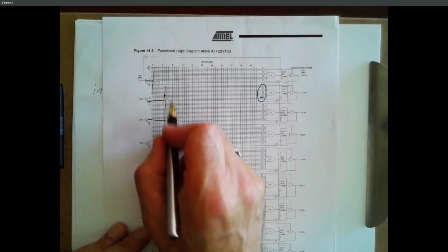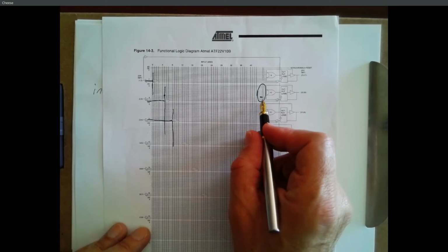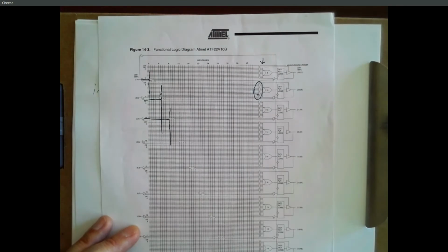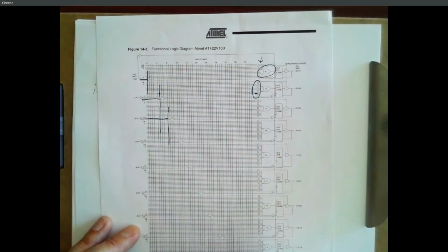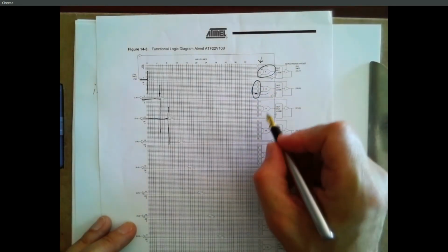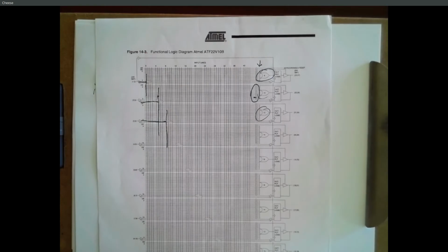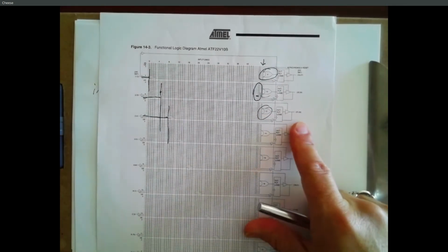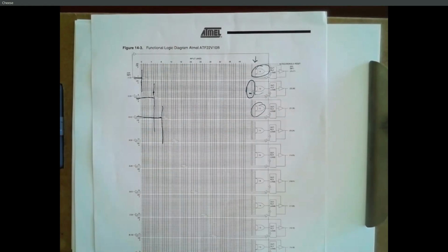And we can have multiple inputs driving inputs of that AND gate. And so we can generate product terms along here. And those product terms in this particular device, they all get ORed together. So there's an OR gate, OR gate. And then the output in a pure PLA or PAL or PROM would just go into an output port. On these devices, they actually go into flip-flops, and they have some feedback, so we can build sequential elements.